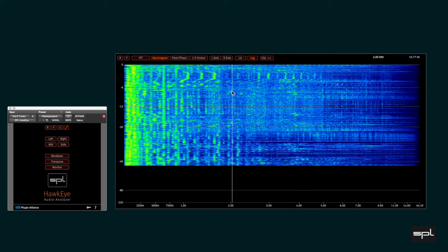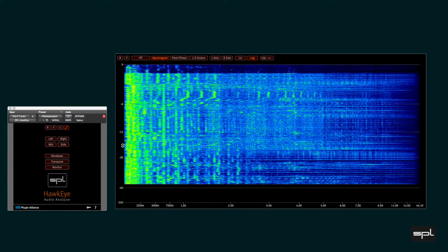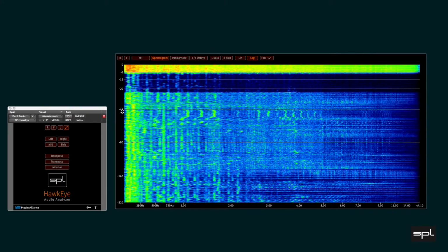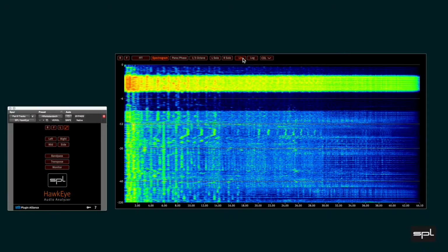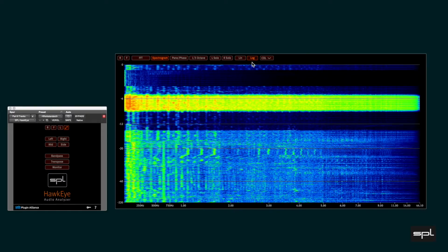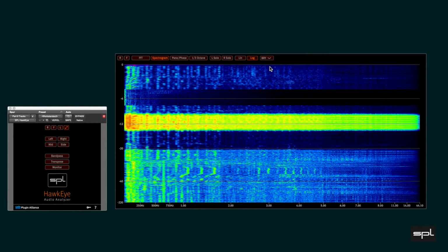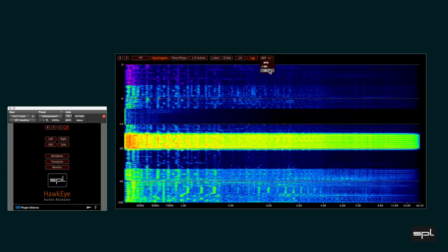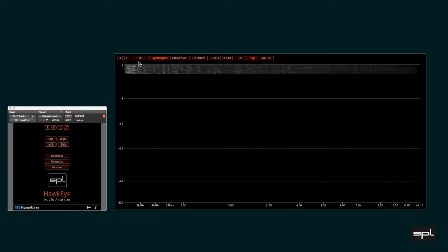And dragging of the amplitude axis stretches or compresses the dB scale, which has a direct influence on the brightness of the waterfall plot. The linear frequency scale is fixed and the logarithmic frequency scale can again be stretched and compressed. The drop-down menu offers a selection of color schemes: blue, red and yellow, full color or monochromatic grayscale. The grayscale is best being used when laying the spectrogram behind the FFT, like this.